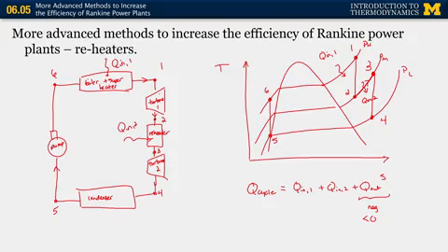If this is a means to improve the performance on the high temperature end of the cycle, we can do the parallel on the low temperature end. And so we can add intercoolers. So there are all these strategies for adding components and packaging them in different ways in order for us to improve the cycle performance and improve the work out of the turbine. And we're not going to go through all those permutations and combinations. I can tell you that, again, we're not even at the most basic form for a power cycle. Most of them will have multiple stages of turbine expansion, multiple reheaters.